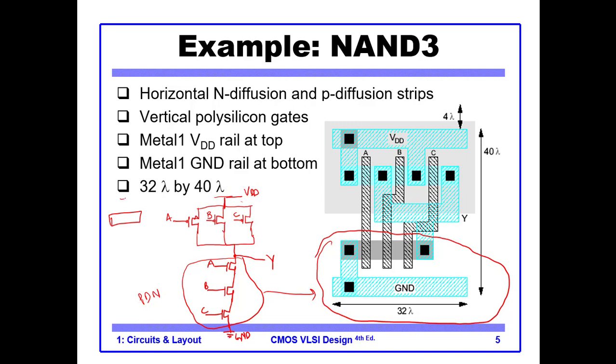You have this substrate, and on top of this substrate you have the polysilicon strip, this one. Whenever you have this kind of plus sign, on one side a source and on the other side a drain will be formed, and this strip of polysilicon is your gate. This is the same for NMOS and for PMOS. They both look like this in the layout view. Just keeping in mind that concept, we see that here is our transistor A.